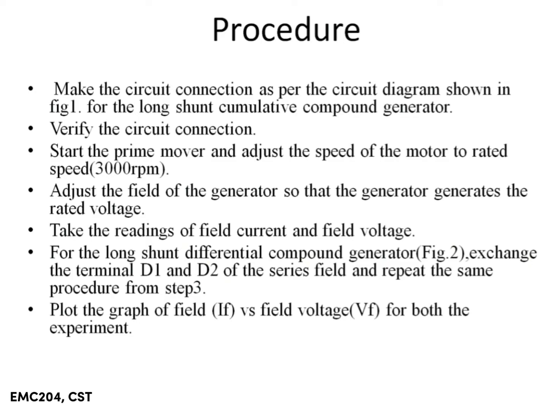So these are the procedures of this experiment. Number 1 is to make the circuit connections as per the circuit diagram shown in figure 1 for the long shunt cumulative compound generator, which I have said. Then verify the circuit connection. This is the most important thing. Before giving the power supply, you need to verify the circuit diagram.